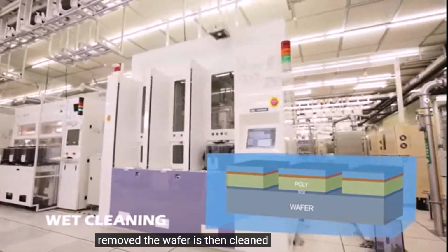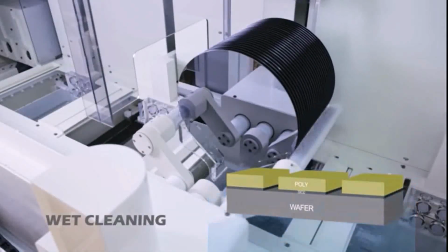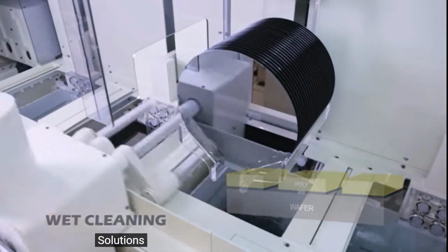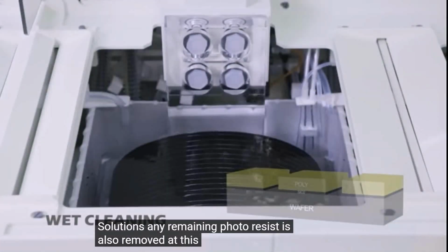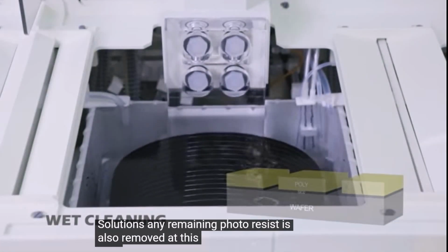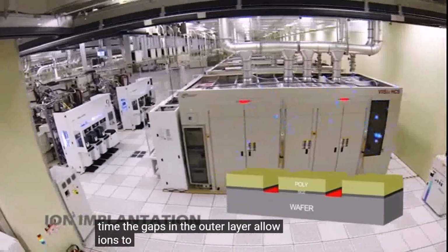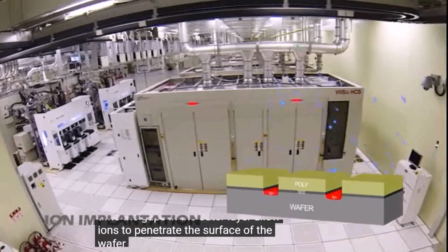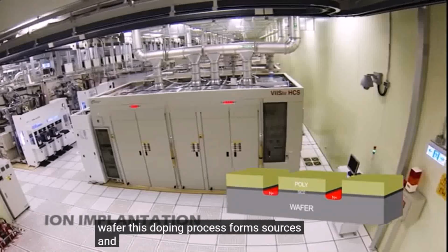The wafer is then cleaned by chemical solutions. Any remaining photoresist is also removed at this time. The gaps in the outer layer allow ions to penetrate the surface of the wafer. This doping process forms sources and drains.